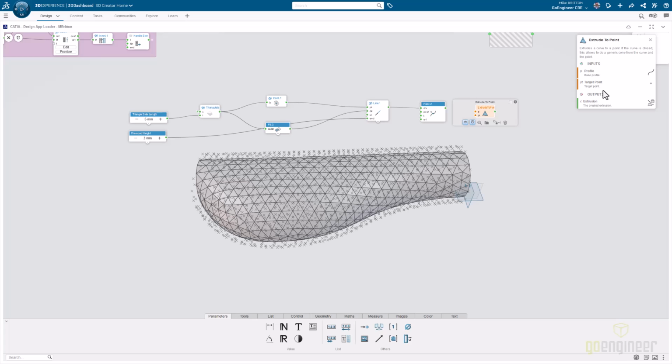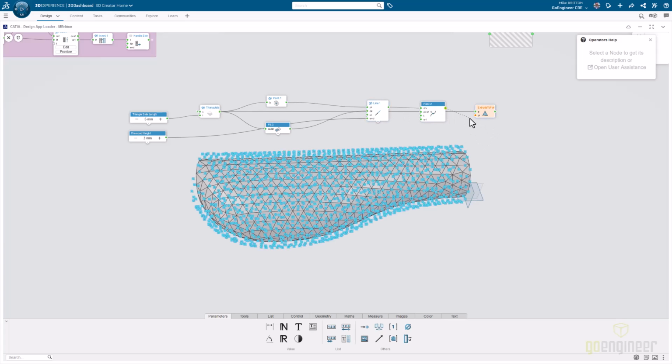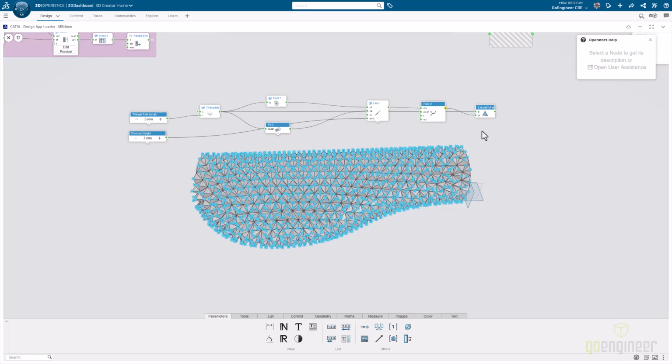My base profiles are all going to be from the triangulate command back there. So once again, disordered, I can reach way back out here and put it out to something new. And the end point of all of these extrusions is going to be those endpoints that I just made. If I hide those, we can see that we have this wonderful spiky surface that we've created.